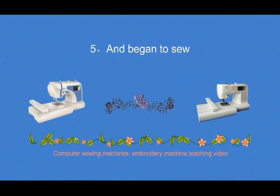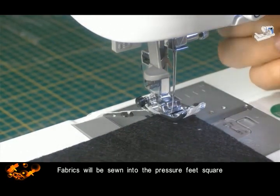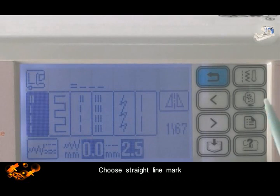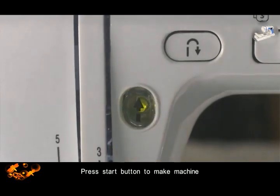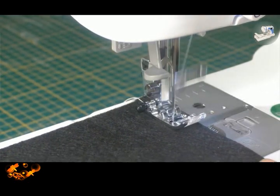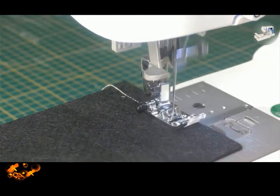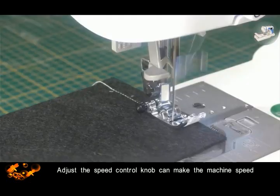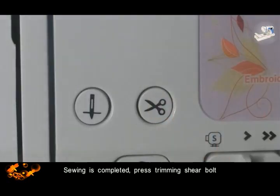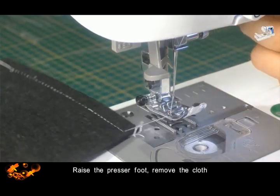5. And begin to sew. Open the power supply. Place the fabric under the presser foot. Choose the straight line stitch. Press the start button to run the machine. Adjust the speed control knob to change the machine speed. Sewing is completed. Press the trimming button. Raise the presser foot. Remove the cloth.